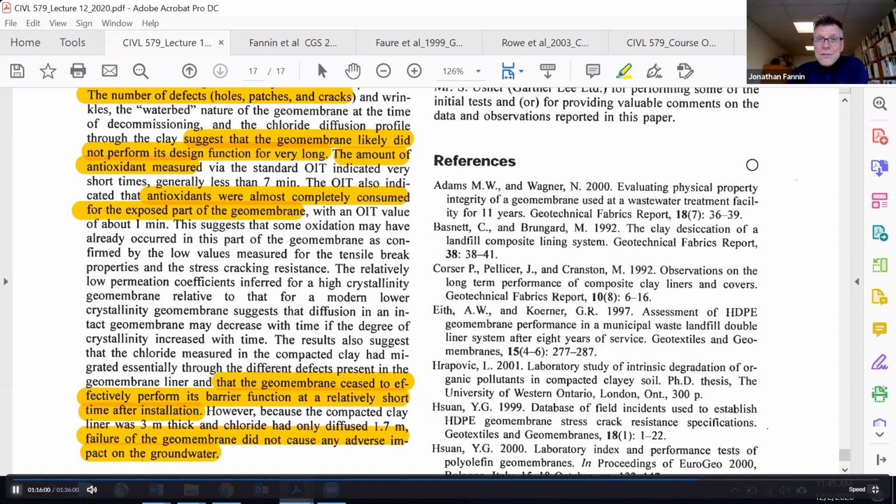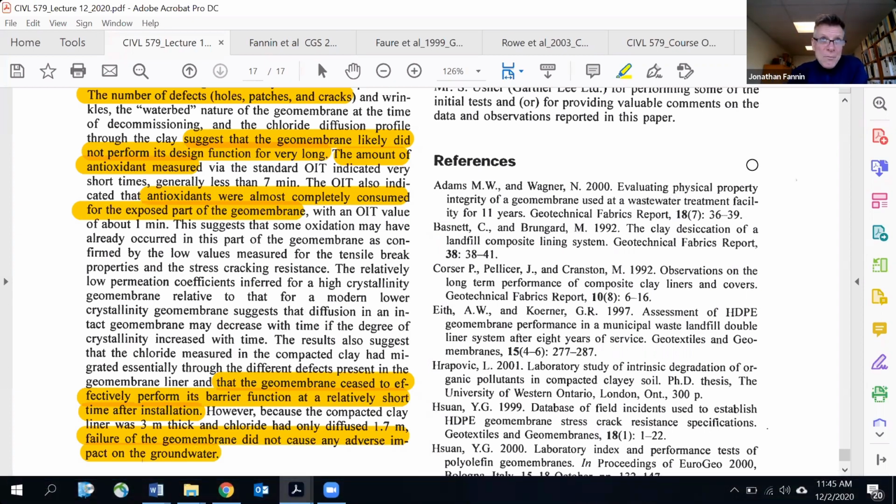And were I to wrap it back up with embankments, probably a geosynthetic doesn't have to be in an embankment for more than about 3 or 4 years. Any contribution that it would make to the stability of the embankment is done as the strength of the embankment gains with time, the strength of the embankment foundations, right?